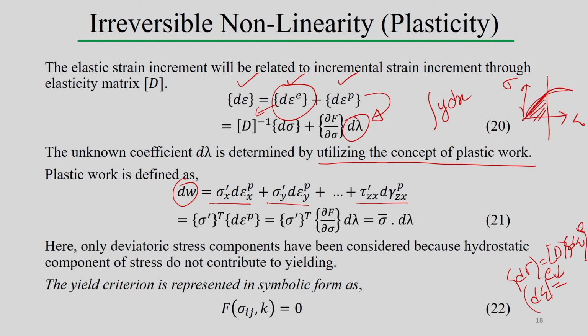So, if you consider a very elemental part, what is this elemental area? If this is the strain component and the corresponding stress is there, then sigma d epsilon is the incremental work done for this element, and this work done represents the value per unit volume. Simply multiplying stress into incremental strain indicates the work done per unit volume for this element.